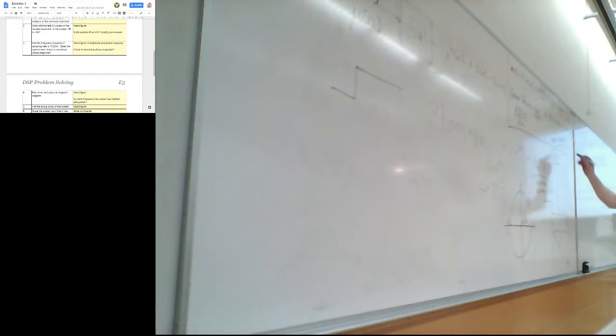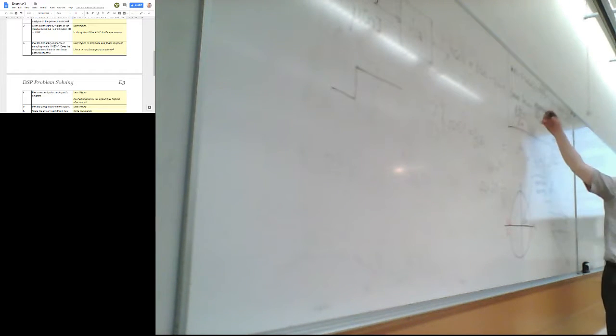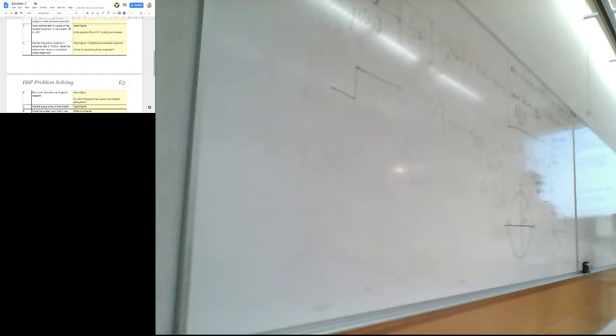And then the other part is phase response, and if the system does not allow much distortion on group delay, meaning the group delay must be about constant on this passband, then you need as linear as possible phase shift. Okay.